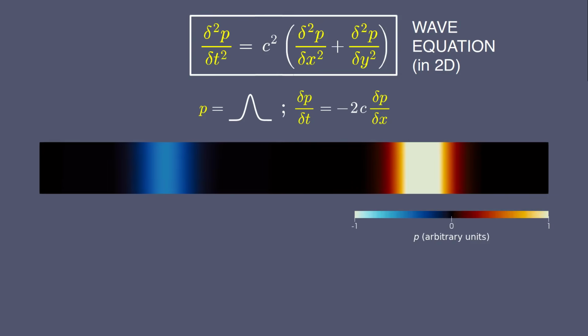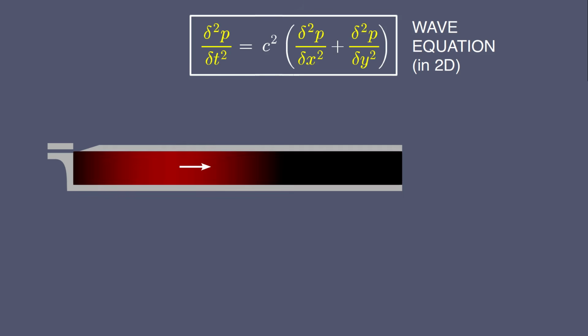Because I want to point out that there's nothing strange about the end of the pipe, where waves end up travelling in various directions. Pressure does naturally want to propagate in all directions. What's special is when we have a unidirectional wave inside the pipe, then the wave satisfies this very special relationship. Now if we have this relationship, from that we can derive that the second derivative is like so. But that's the wave equation in one dimension.